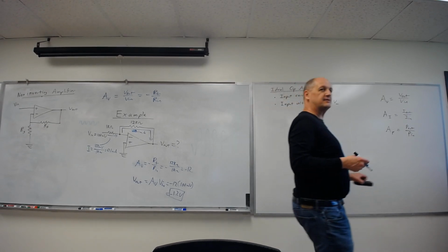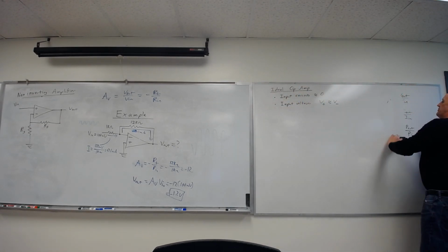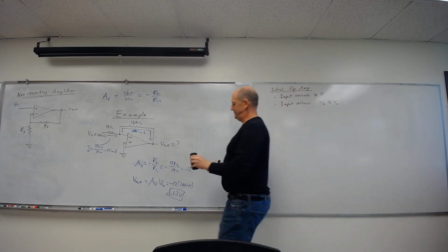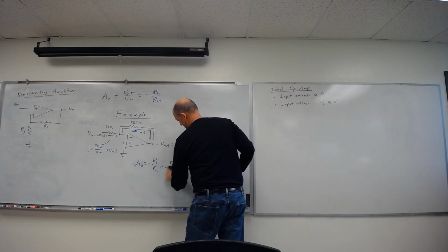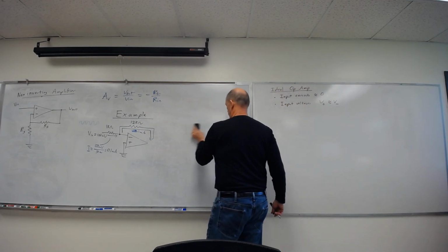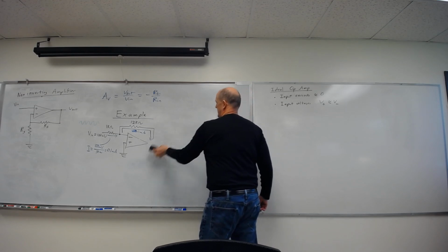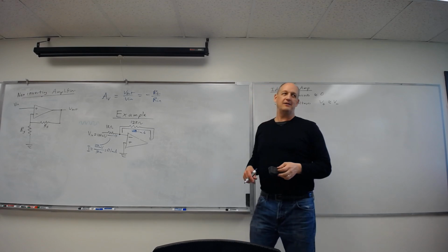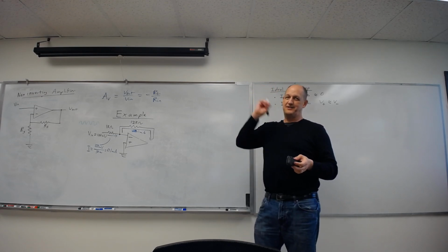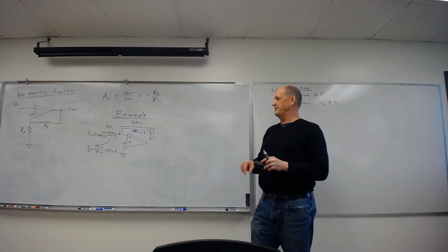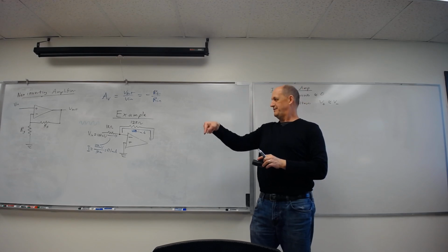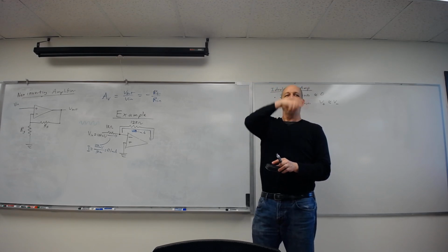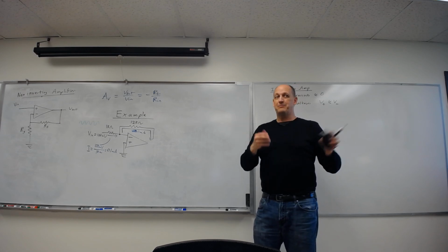Incidentally, just out of curiosity, can you think of a circuit where I could use positive feedback? It's fine if you don't. But an oscillator circuit. So I don't have an input, I just take the output and send it back to the, well, I do have an input, but it's the output. I just send it as positive. And then if I use an inverting amplifier and do positive feedback, it keeps going back and forth to the rail voltage. So I just have a DC power that produces a clock out.